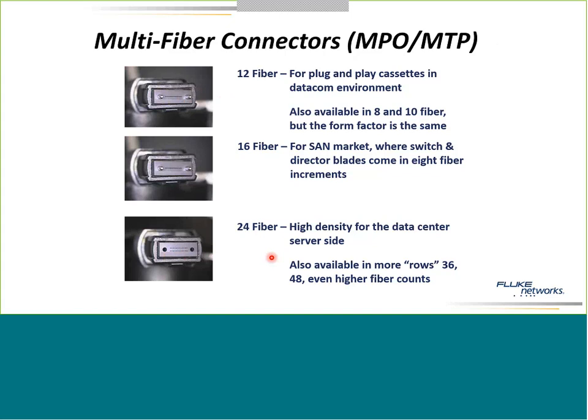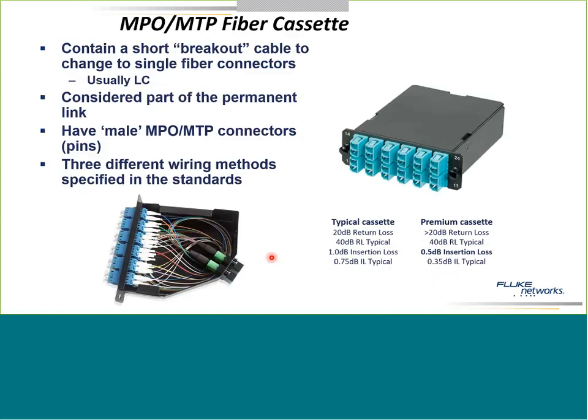Now, one other thing that I want you to notice in these pictures, we can see that there are pinned and unpinned versions of these connectors. There's the pinned version, and here's the unpinned version. In order for these to properly mate, of course, we need a pinned to an unpinned connector. And pin-to-pin does not work, and unpinned to unpinned also is not going to work. You're not going to get a good alignment with the connectors. That may be a source of your problems.